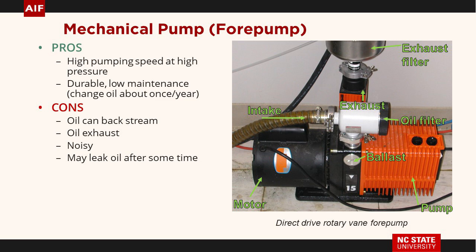If you've got MOCVD or something like that, you probably do. And you may bleed air into it, so the pump oil is not getting such nasty stuff in such high concentrations. These are pretty good. Maybe you change the oil once a year. What's the problem? Oil. And oils, many of these, after several years, it may leak, in which case you may be in for a new pump.